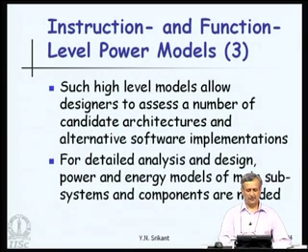However, for very detailed analysis and design, that is design of the hardware, power and energy models of main subsystems and components are also needed. In other words, we will need microarchitecture level, ALU level, memory level, cache level, interconnection level models in order to study the design and then make an estimate of how much power is consumed by that particular design.